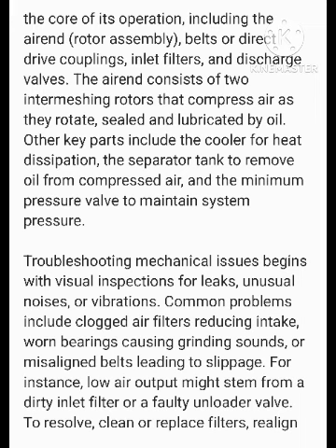The air end consists of two intermeshing rotors that compress air as they rotate, sealed and lubricated by oil. Other key parts include the cooler for heat dissipation, the separator tank to remove oil from compressed air, and the minimum pressure valve to maintain system pressure.